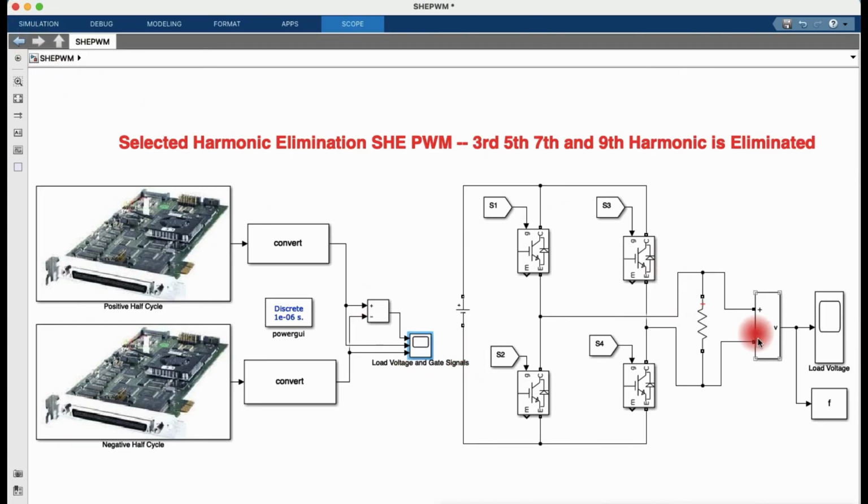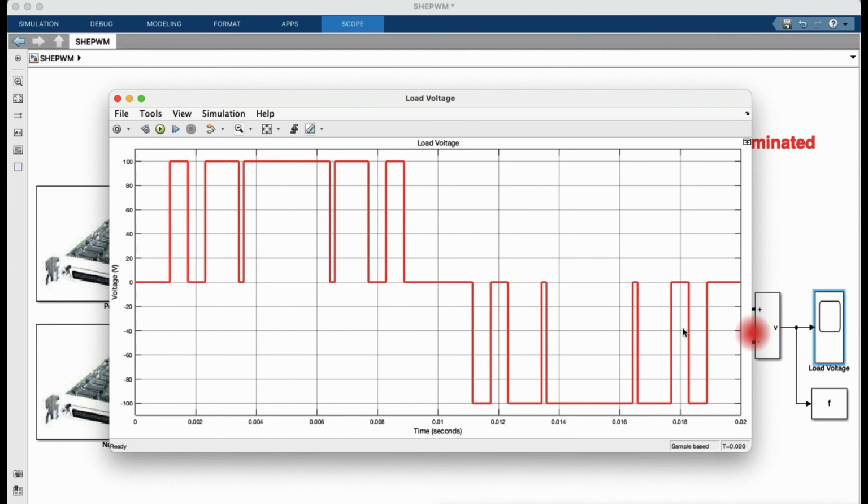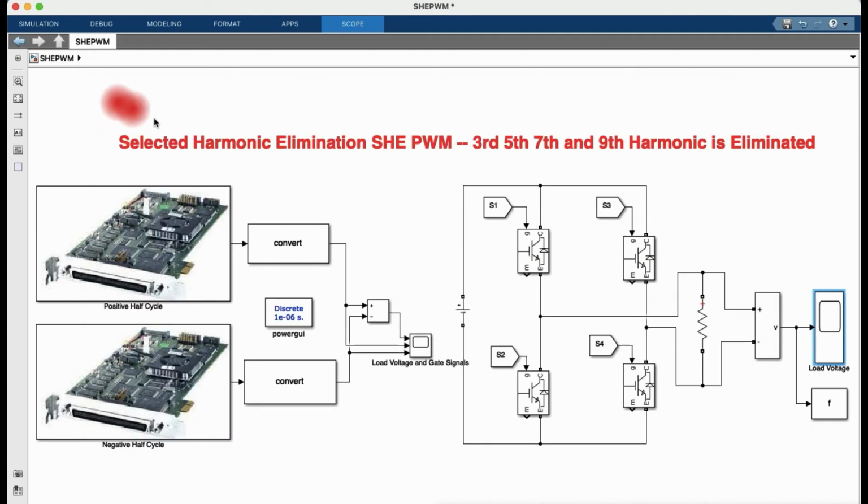Okay, now these signals are applied over here, so you can look at the output voltage waveform, that is this one, and that is just a magnified version of what we were seeing earlier. Let's suppose that the DC voltage source is 100 volt, so we will be getting this as an inverter output voltage waveform, and then we are going to store this value in the variable f. So now we will run the Fourier series code looking at this variable f, and then we can display the spectrum of the inverter output voltage waveform.